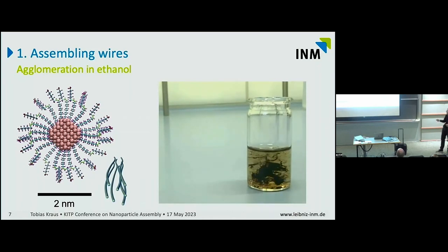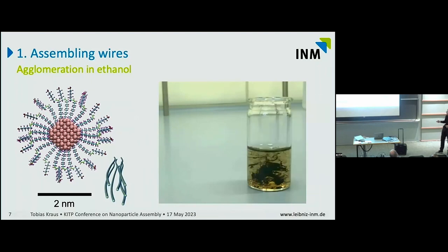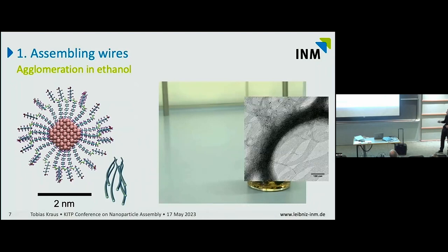It actually creates this jelly kind of feathery network where these wires, thanks to their large aspect ratio, are all connected. And the trick is basically that bundles form in which these wires are next to each other. This is in the electron microscope. And because they have a very high aspect ratio, the probability of one wire being a member of multiple bundles, of course, becomes very high. So it is very easy to create arrangements where they're all interconnected, which is why we were very interested in these things for electronics or for any application where you would like to have percolation.